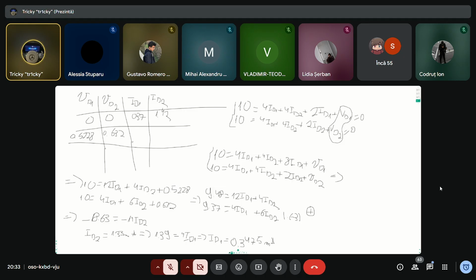So we can go back and replace in the formula now with our new currents. VD1 is equal to, I was going to write it directly, 1.2 times 0.025 ln of, where is ID1? 0.3475 divided by 10 to minus 8. And again, let me plug this into the calculator.